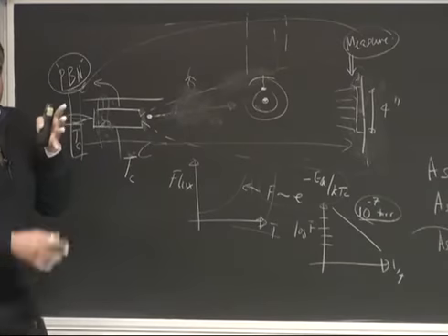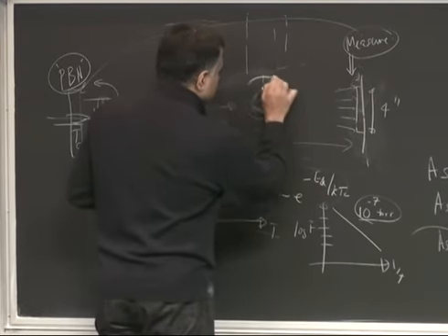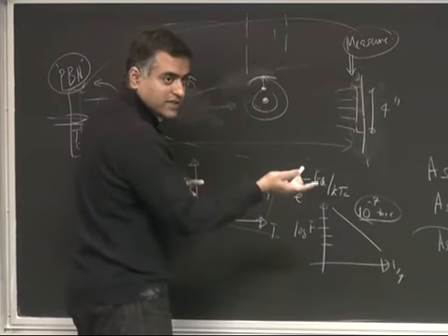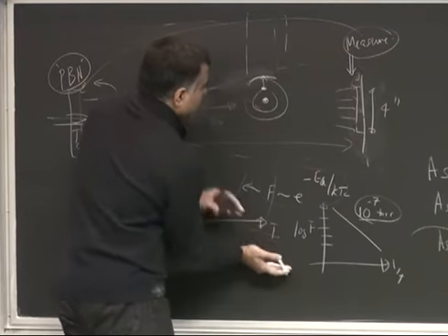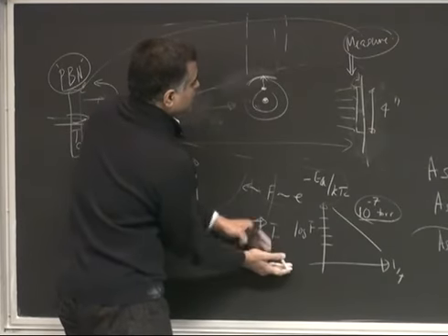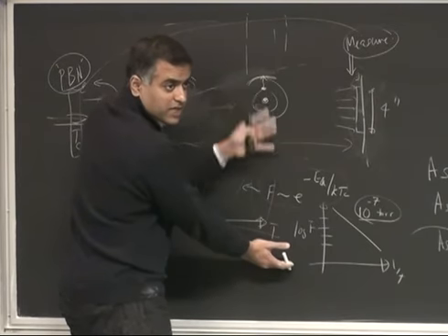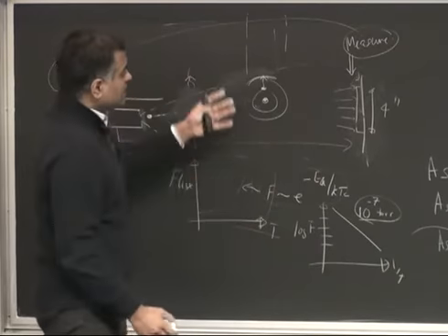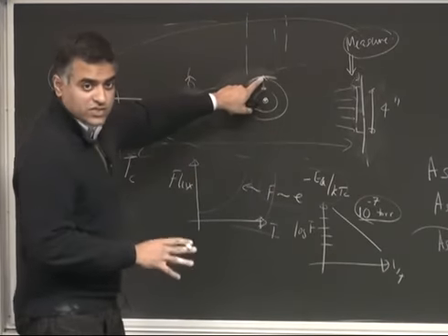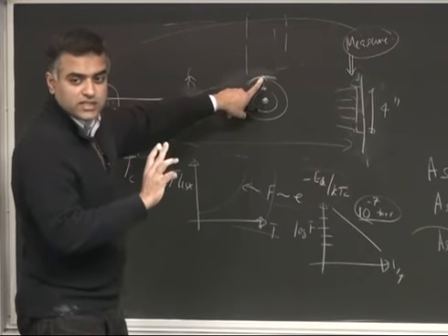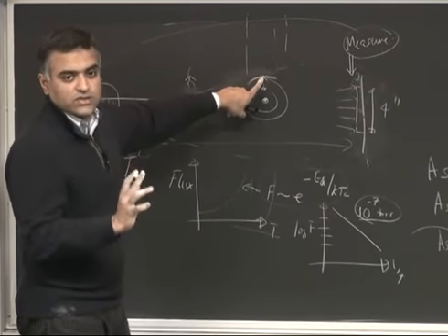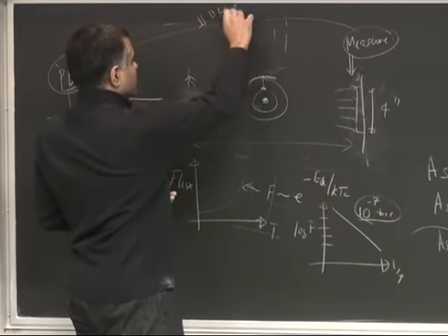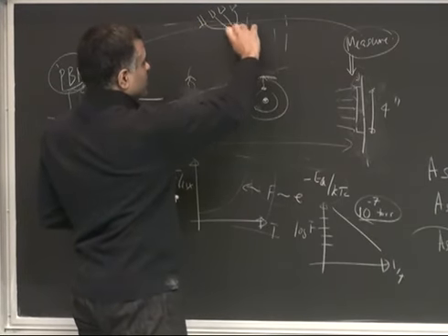If light goes through and the photon energy exactly matches two levels, it will get absorbed and re-emitted, and by looking at how much got absorbed, you can figure out how many atoms of the gas there are, because the absorption changes with the number of atoms. But then you need a laser for every transition. If you want to track gallium, you need a unique wavelength laser. If you need aluminum, you need another, and so on. So typically they have multiple laser sources, one for each atomic transition, and you can obviously pump them all into one optical fiber.